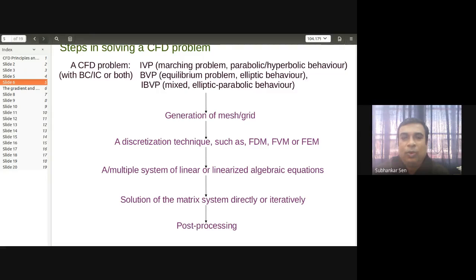So when you have the original equation before discretization, that is the generic equation or the continuum equation. Now you have to write that at every discrete point, the points you are generating in this step. These points are known as the nodal points. So based on these discretization methods, at these nodal points, you will write algebraic equations. So the partial differential equation or the ordinary differential equation will be converted to algebraic equations. This conversion method is known as discretization.